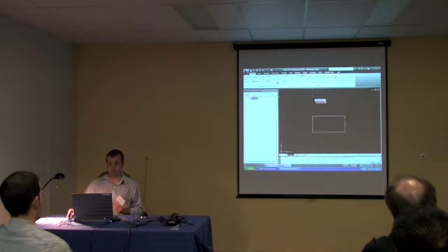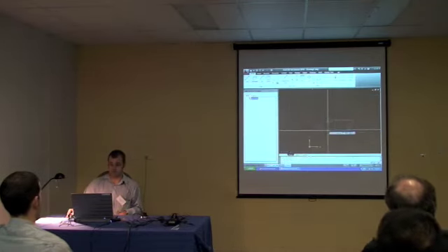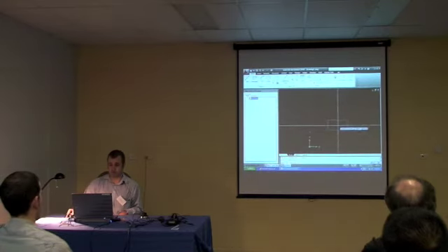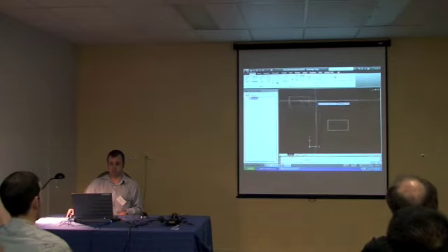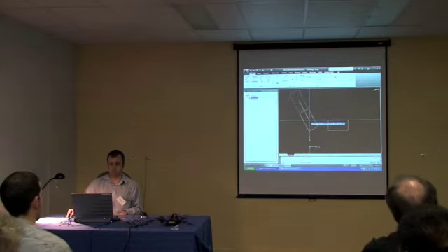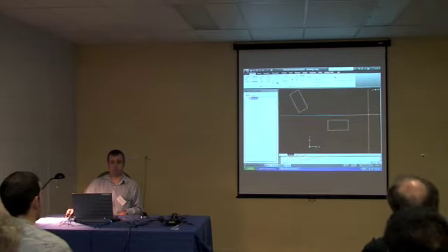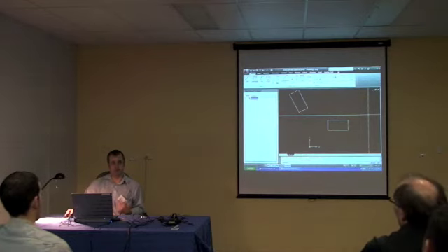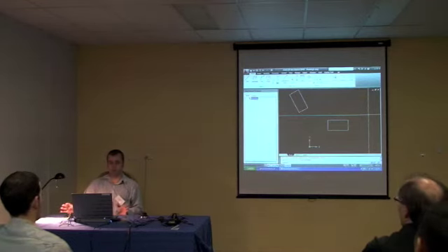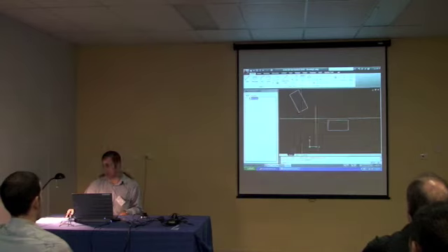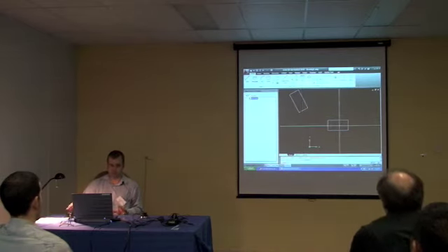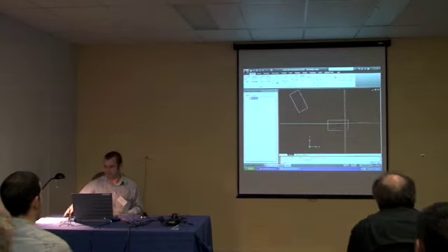Here we'll make a copy of it. So here's my object. Where's my base point? I'll try and pick up about there. I'm going to move it, then I'm going to rotate it. And it's done. It's copied. So it's three commands in one. Really saves a lot of heartache.